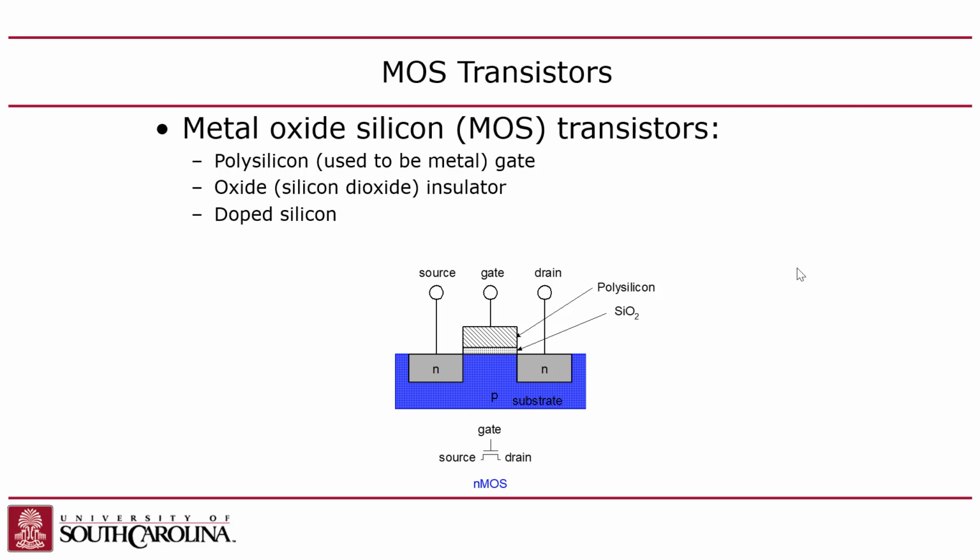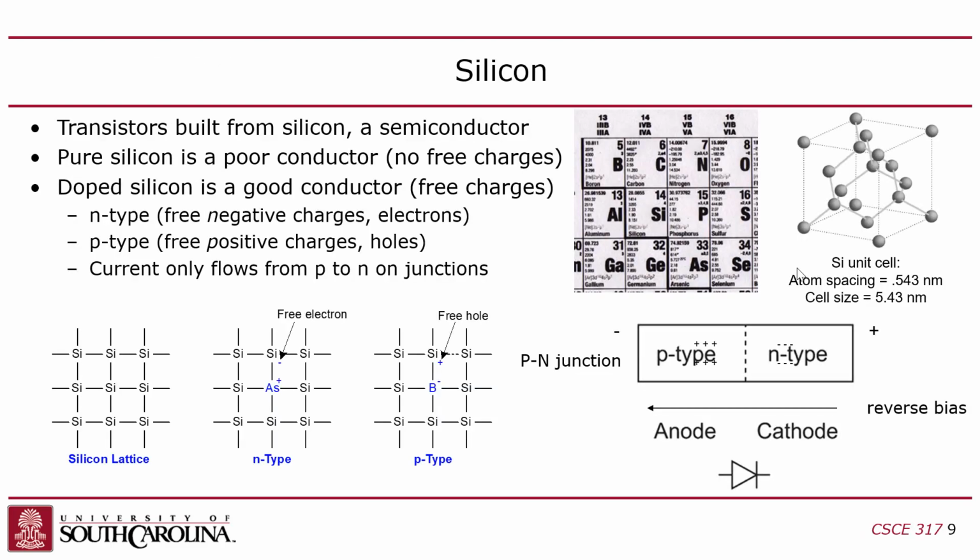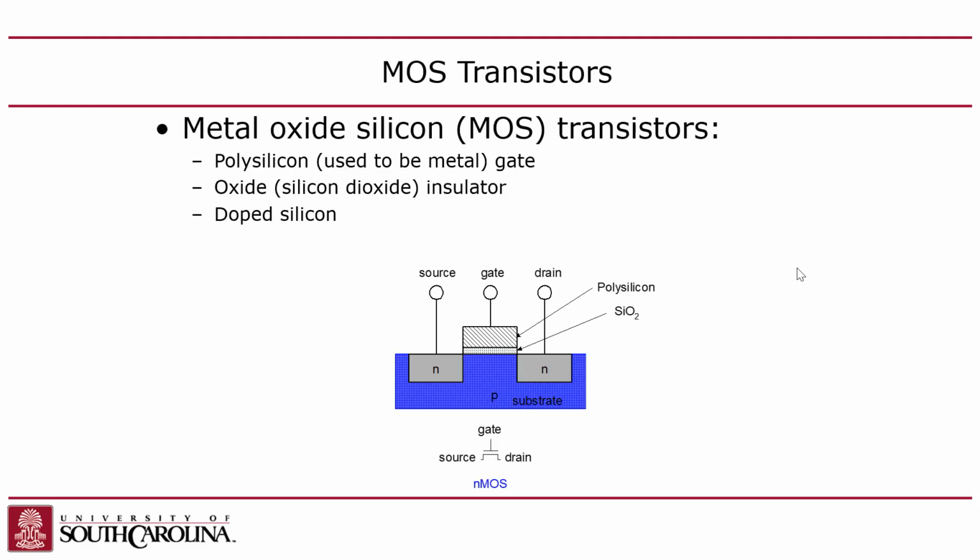And you can actually reverse the doping by doing that. So in other words, even though this p-type might have had one of the p-type dopants in it, what are they? I always forget. Boron, say. Okay, so you might have had boron in the substrate originally, but then you start hitting it with arsenic. So this thing had boron in it, so it was all p-type, and then I start hitting it with arsenic in these two diffusion areas. You can reverse the doping in those areas and make it n-type.